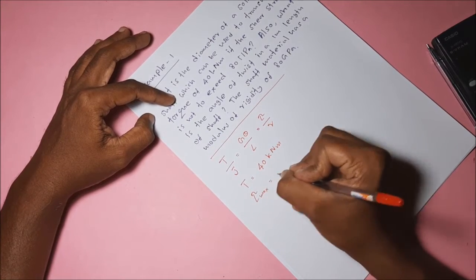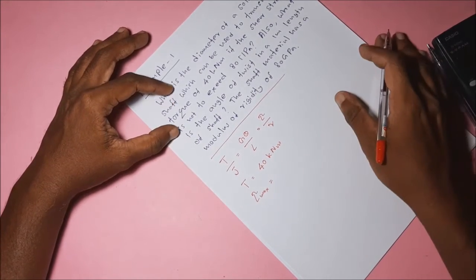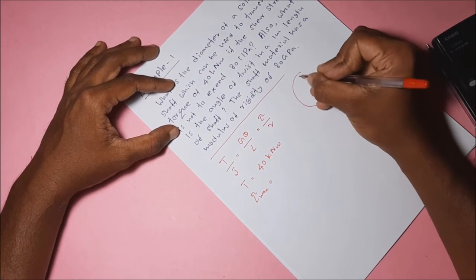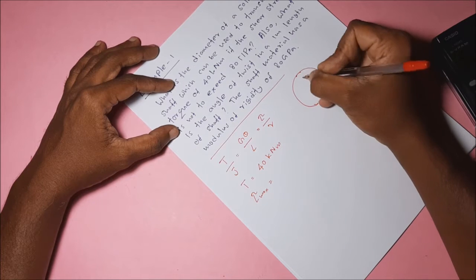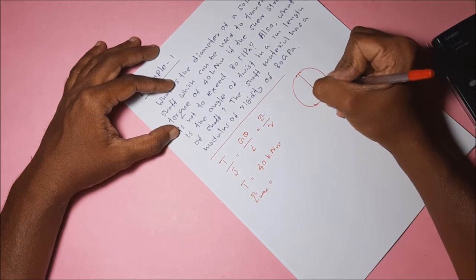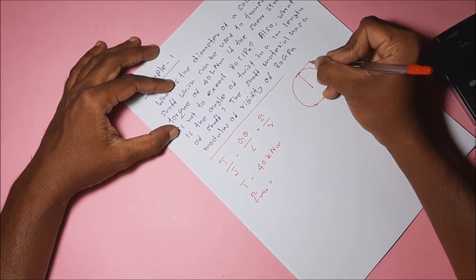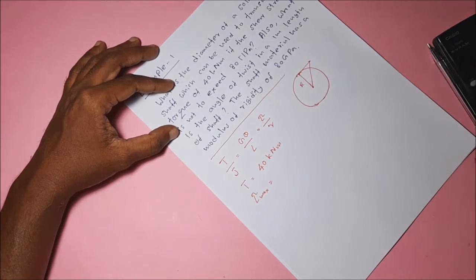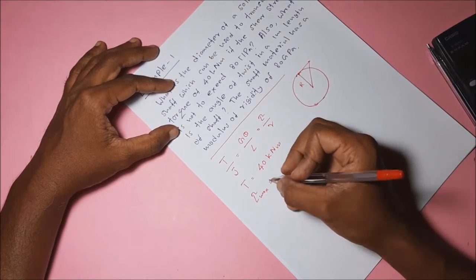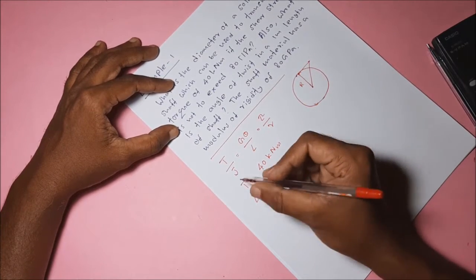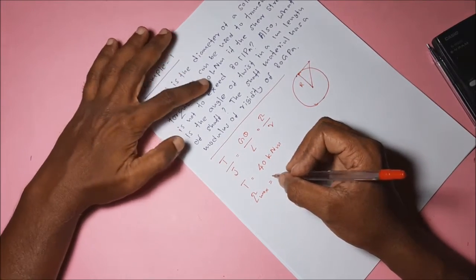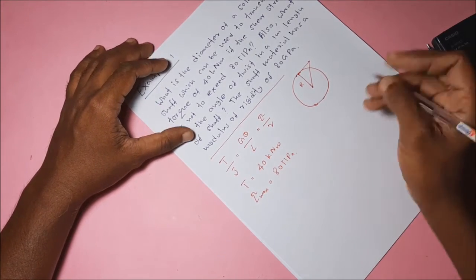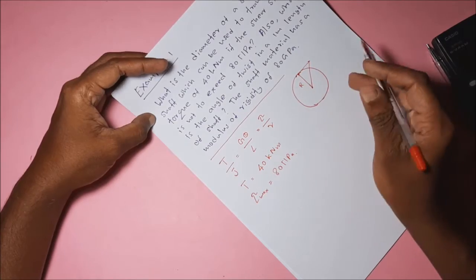So actually, where is the tau maximized? Earlier I explained in the theory, shear stress is maximized at the edge, no? Shear stress has this kind of variation, no? This is the maximum shear stress. That means at the maximum R value, at the edge, it is maximized. R is maximized, tau is maximized. So then tau maximum value should not exceed 80 megapascal. Also, what is the angle of twist in here?